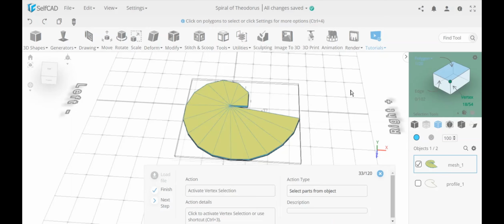If I walk down one, let's say if I go to face selection, you are not going to see visually a change, but technically it's actually going to select all of the faces. And why does it make a difference? If I walk down from polygon directly to edges, it will actually select only the edges that we have drawn, because those are the edges from the polygon. If I walk down from polygon to faces, and then to edges, it will actually select all of these inner edges as well, because those are the edges from faces. Because as you go down, you basically move them down selectively.